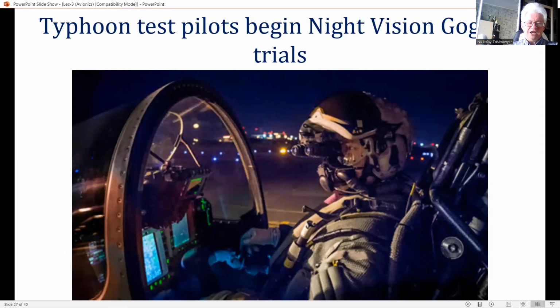This figure shows the Eurofighter Typhoon HMD. This is a binocular visor projected helmet mounted display, which is used by the pilots flying the new Eurofighter type. It has a 40 degrees binocular FOV and has integral night vision cameras, which are electronically combined with the CRT. Clear or IIT imagery can be displayed with flight and weapon aiming symbology overlay.